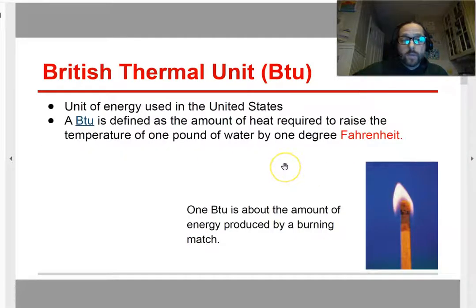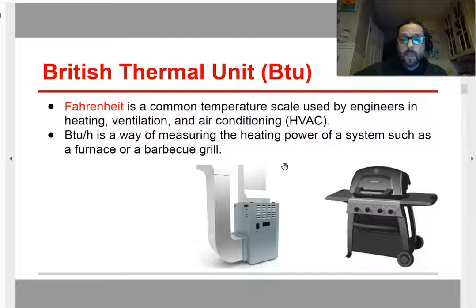We know how heat is measured, so this is very much a review. We know a BTU is the amount of heat required to heat up 1 pound of water 1 degree Fahrenheit. That's something you should know. We know that furnaces are rated in BTUs per hour. It's a little subtlety, but if it says a 100,000 BTU per hour furnace, that actually means that's the input. The output depends on the efficiency.